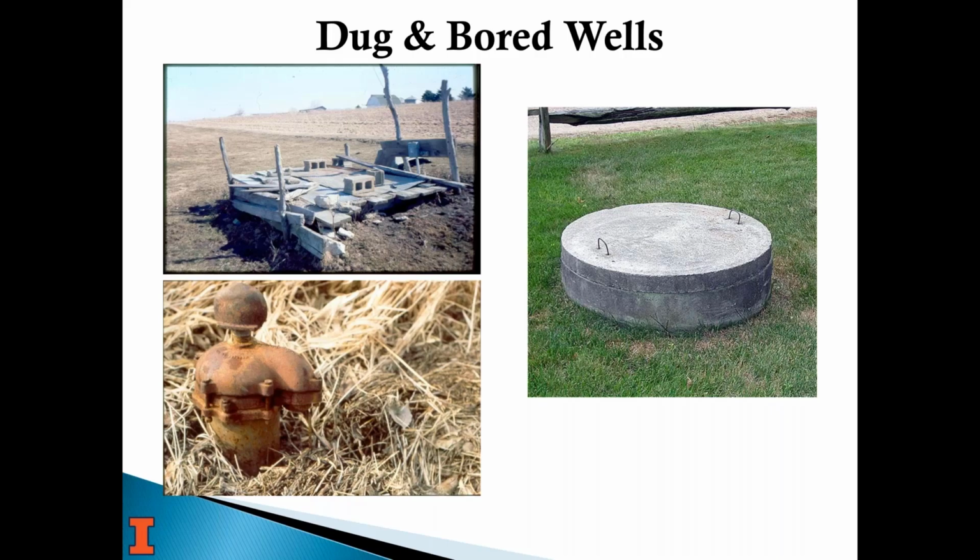And the one on the bottom left is also like the one on the right. It's just that the concrete pad on top doesn't start until 10 feet below land surface. And so there's a steel casing for the first 10 feet and a regular well cap, and it looks like it could be a drilled well. That's just another design so that the upper 10 feet can be filled with clay material or concrete, and it makes it less likely that water from the surface is going to seep down into the well.